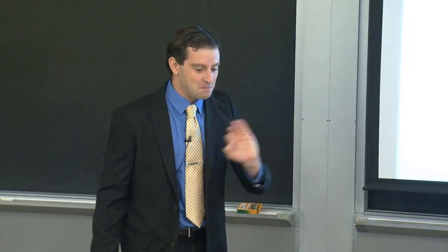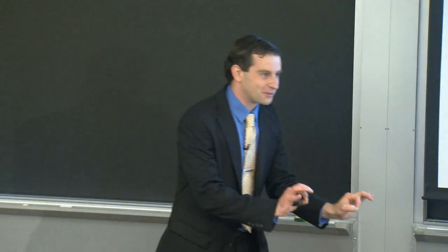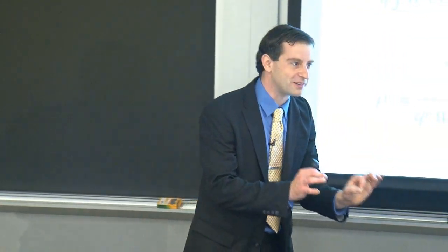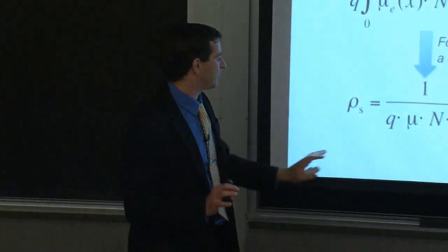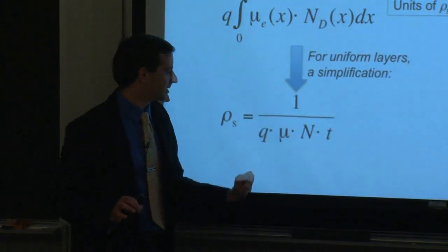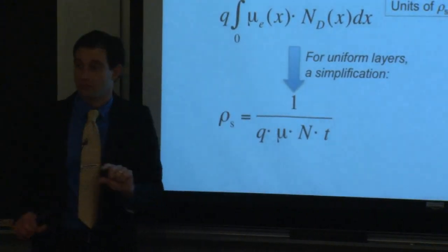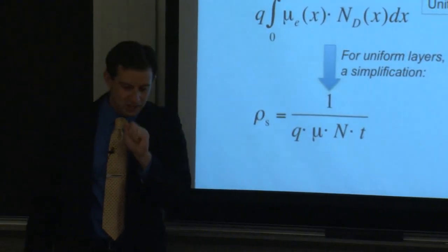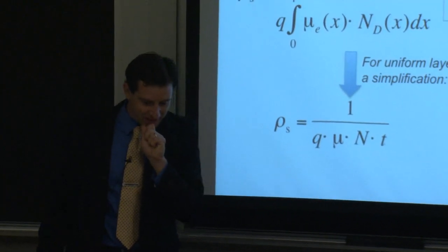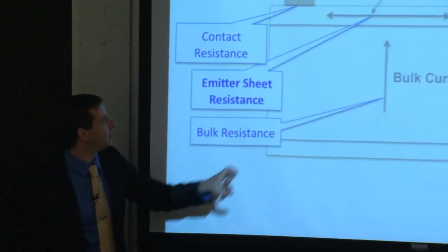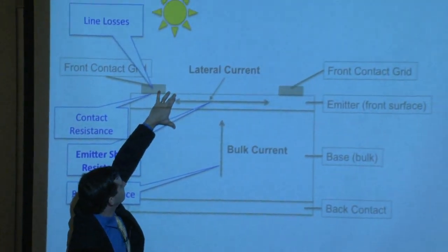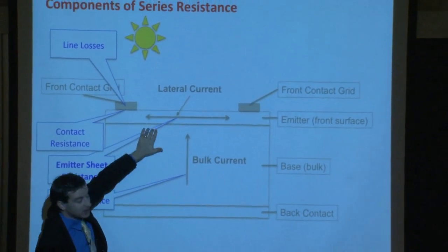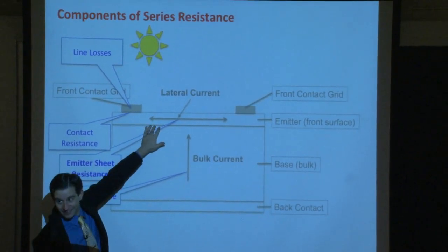And after months of tuning the temperature and the oxygen partial pressure during the deposition process, you're there and you have what you have. You have a certain carrier density and a certain mobility, and you can't do much more than vary the geometric parameter, varying the thickness. So what next? If my thickness is too big on my emitter, I'm going to be absorbing all of my short wavelength photons in the front surface of my device.